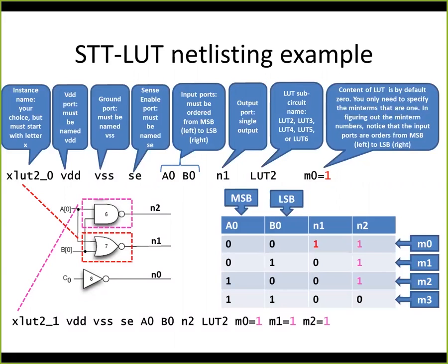So we have sub-circuits of these lookup tables developed already, including the FINFET transistors, as well as the magnetic tunnel junction devices built in. And then students can describe the sub-circuit instantiation of the lookup tables they need based on the netlist that they have come up with.